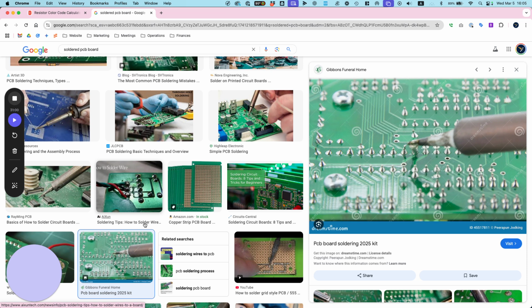That way, when we're doing Ohm's law, V equals IR, we're not going to get confused with the scale of the numbers. I just want to put everything in the same units. It makes things easier. Again, you can work with mixed scales, like kilo and milli, but you really have to be diligent in keeping track of everything. I suggest you put them all in one type. If you're going to deal with all millis, then stay with all millis. If you're going to deal with kilos, stay with all kilos, or just the baseline unit.